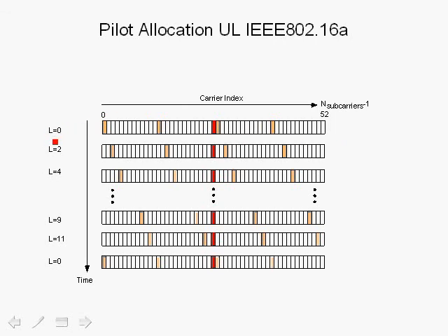Now again we have this parameter L, which goes from 0 to 4 all the way through 11. So it's modulo 12, but it follows this arrangement here. Now for the different values of L, we actually place the 4 variable pilots, and notice that the pilots are at equal distances with each other. So we place the 4 variable pilots for the case L equals 0.